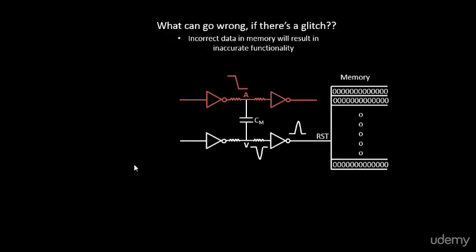We have talked about all of this phenomenon in the crosstalk videos which have been uploaded on Udemy. You might want to have a look into those videos. So yes, this is the technique. By shielding, we are breaking the coupling capacitance between the aggressor and the victim. We place a wire over here and a wire over here, and either both the shields are connected to VDD, or both are connected to ground, or one is connected to VDD and one is connected to ground.